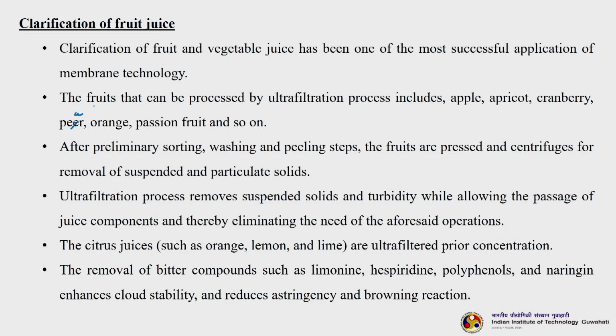So, the fruits that can be processed by ultrafiltration include apple, apricot, cranberry, pear, orange, passion fruit and so on. After preliminary sorting, washing and peeling steps, the fruits are pressed and centrifuged for the removal of suspended and particulate solids. Now, the ultrafiltration process removes suspended solids and turbidity while allowing the passage of juice components, thereby eliminating the need for the aforementioned operations.